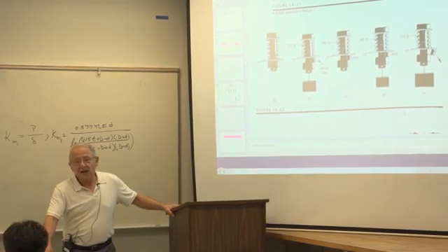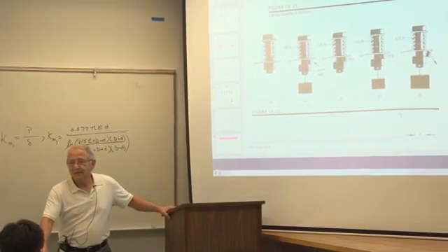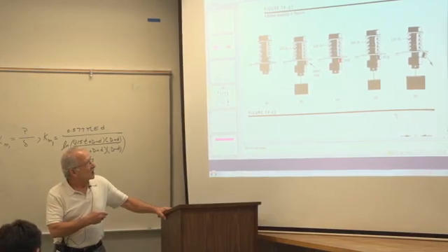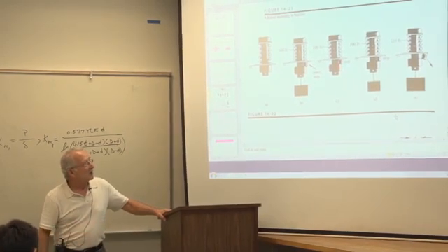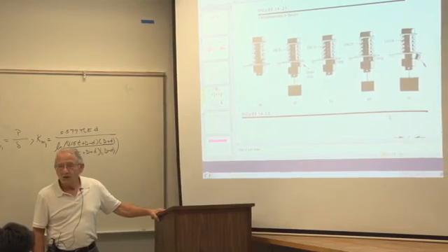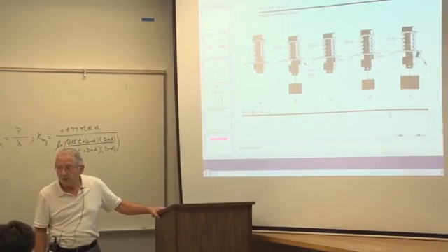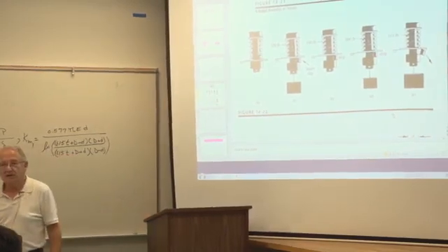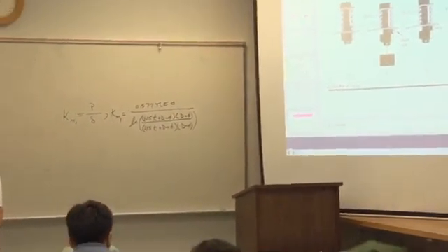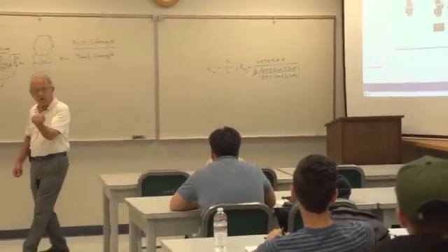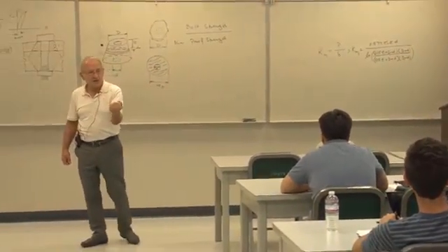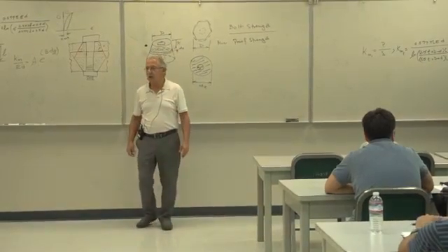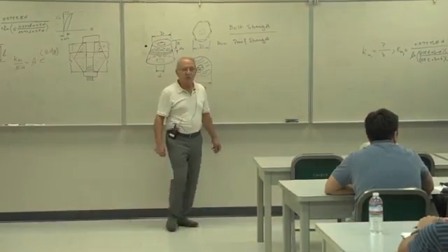And of course, it's not magic. What's the force in the stop in this case? 100 pounds, right? What's the force in the stop in that case? 50 pounds. Because you've taken 50 pounds off of that 100 pounds. So all of it went into the member. That stop is now acting as the member. All of it went into the member.